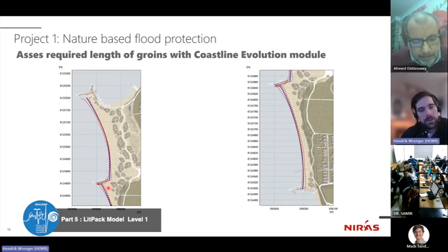So there are some tools available to use the coastline evolution module, even where we have interruptions of our littoral transport due to structures, so we don't have that uniform beach anymore. But we just need to really recall for what context these available models of the different structures are made, and what exactly the constraints are.